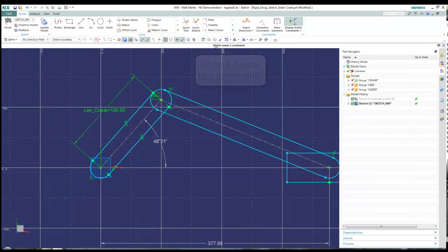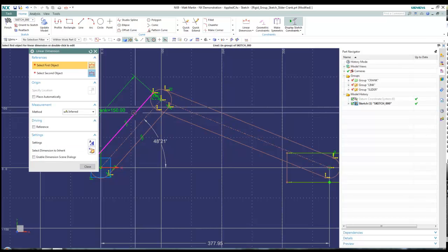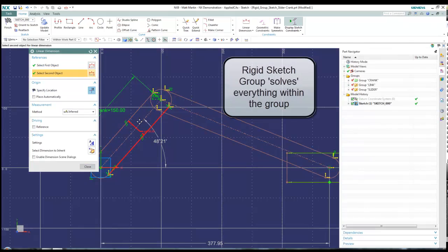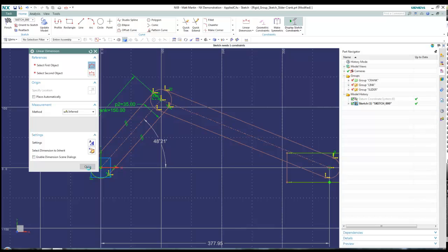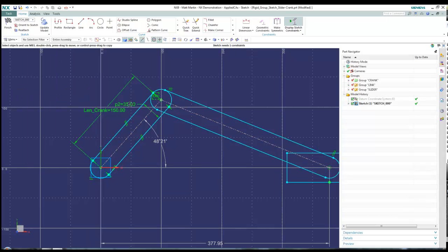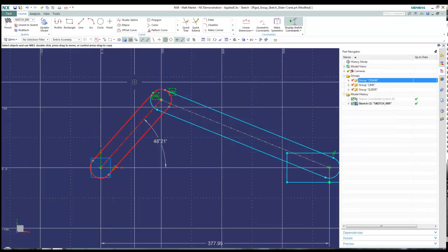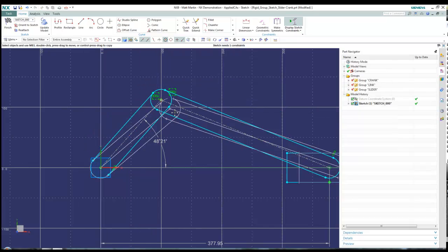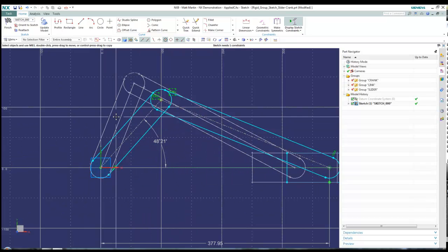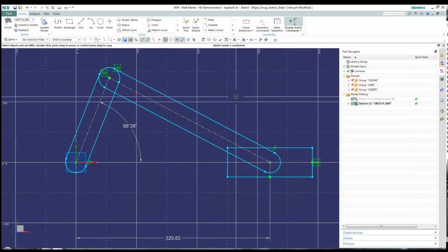constrained within it. So I've got my length. On this one, I now require 2 constraints to finish it, and one of them is the width of this bar here. So I can pull that out. Set that to 35, and I'll right click and deactivate that, and now it's rigid constraint again. And I can rotate that around. The graphics on this probably isn't coming through as well as I'd like it to.